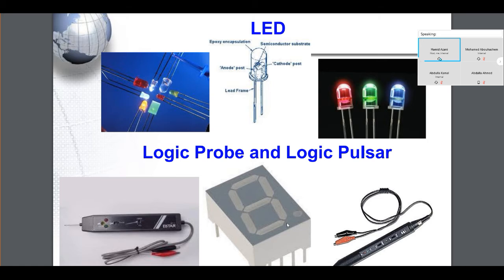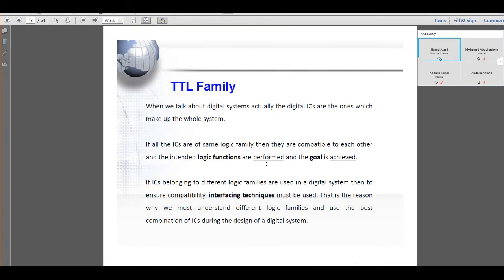You take your component, which can be a 7 segment, LED, or whatever, and there you find, for example, the part number for that component. You type that part number. You can just add as a keyword any significant word that will help in searching for the right component. In Google, you can find the PDF data sheet, and you can browse through it. I will show you one example later on. You can check all the information you need. You'll find it in that data sheet, given by the manufacturer of that component.